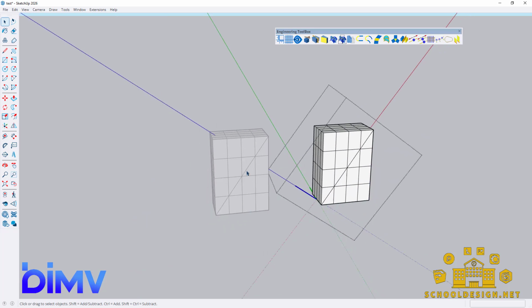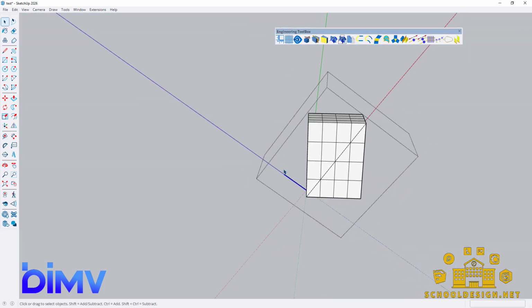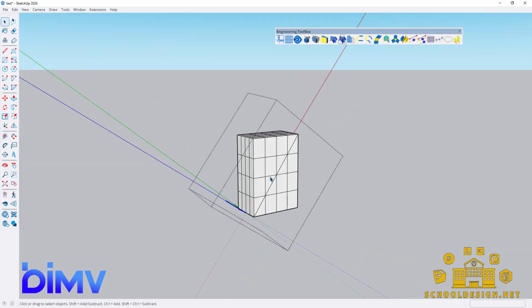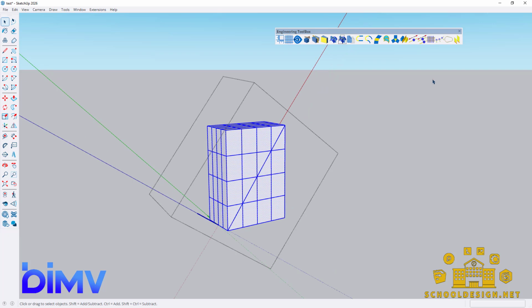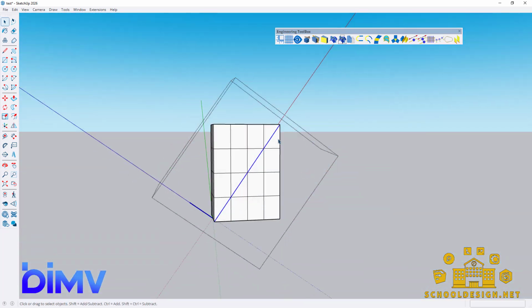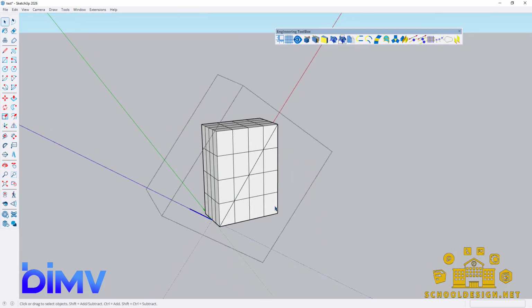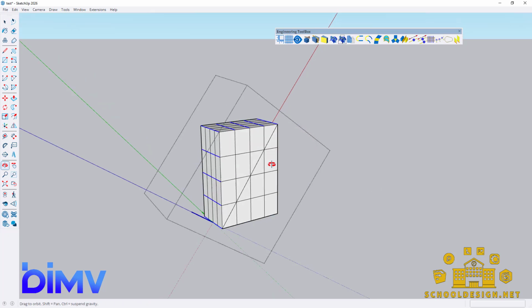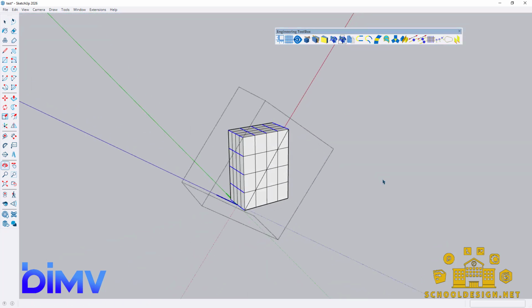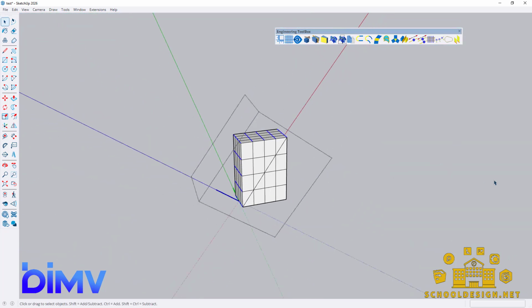If I go into the components, we will see that my component has those axes facing in a different way. I would like to select all the edges along the red axis. I select the elements, the plugin, I mark the red, tolerance 5, and at this moment I choose the local system. And I have them selected. Well, only those that are in the direction of the red axis. If I want it in the direction of the green one, similarly I mark green, local, OK. And I have all of them selected in the direction of green.